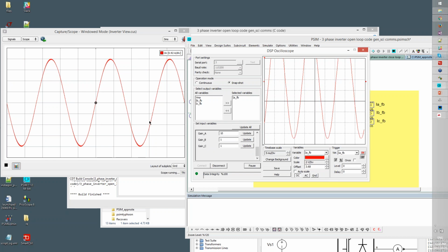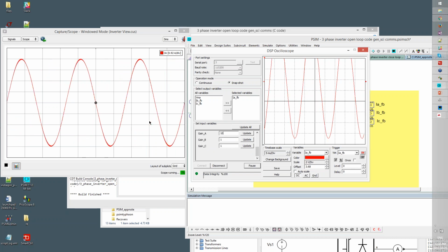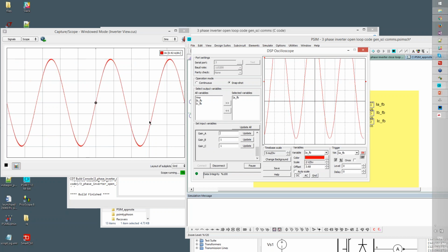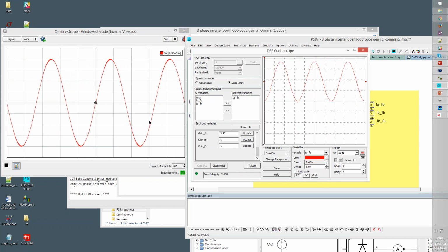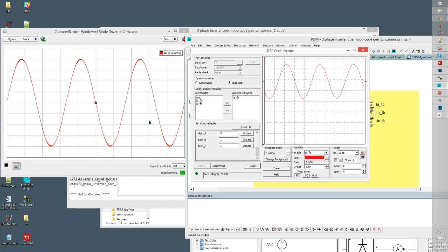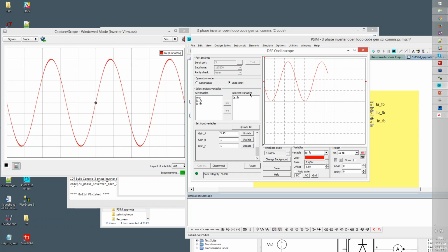So we'll adjust the gain in steps here. So 10 is too much. Maybe we'll try 3.45. Oh, there's the magic number. Obviously, I already knew beforehand what it was supposed to be. But yeah, originally it was a gain of 1. We increased it a little bit, and we can change this gain on the fly so that we can get it to be correct. So we'll go 3.45, and we can see that that's now offset perfectly, and we can zoom in to see that touching the negative side is perfect.